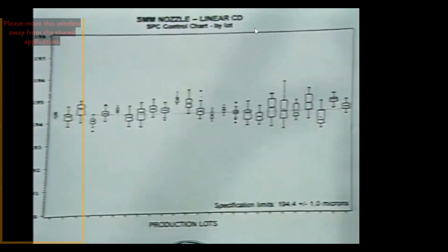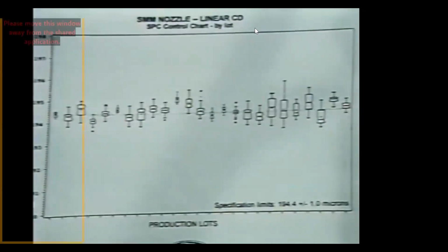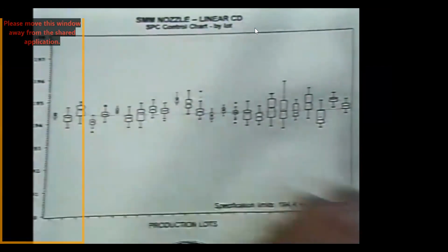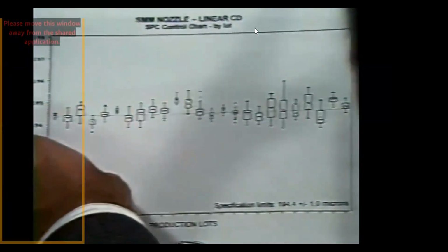Our inspection equipment had gauge capability down to 1/4 of a micron. So we would inspect every single orifice automatically. You'd load this machine, step through, and acquire data. Those units that exceeded the specification were rejected. Our typical lot yield was on the order of 60 to 80%. This particular lot represents about 50 wafers worth of material, and there are 400 units on a wafer at 4 nozzles per wafer, so there's an awful lot of measurements associated with that.